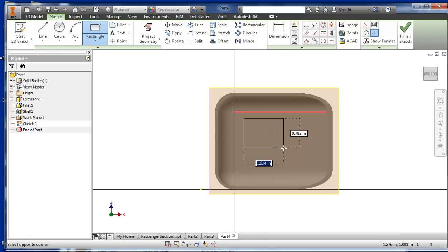Okay, the width right now, I can see on the paper, they don't show the actual width, they've used a baseline dimensioning, they showed the width from the left side all the way to the right edge here of the underside. Well, Inventor can do the math for you. If you can see that that dimension is 2.22, that width would be too long as it goes all the way to the right side. So we can just say minus and then subtract what distance it is from the right side of this rectangle to the right side of the windshield. And that's the smallest baseline dimension there, 0.68. So you can actually just type in the math there, 2.22 minus 0.68. Inventor will do the math and give you the correct dimension.